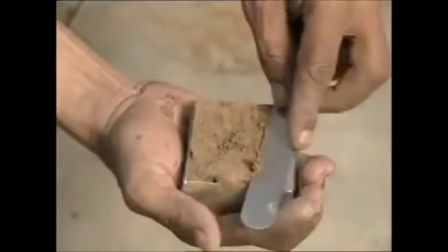So next, make sure that the soil or the sample has a flat surface. This flat surface helps us reduce or avoid the presence of gaps. By removing the gaps, it also provides a good shape so that we have few voids. So this is a shear box.